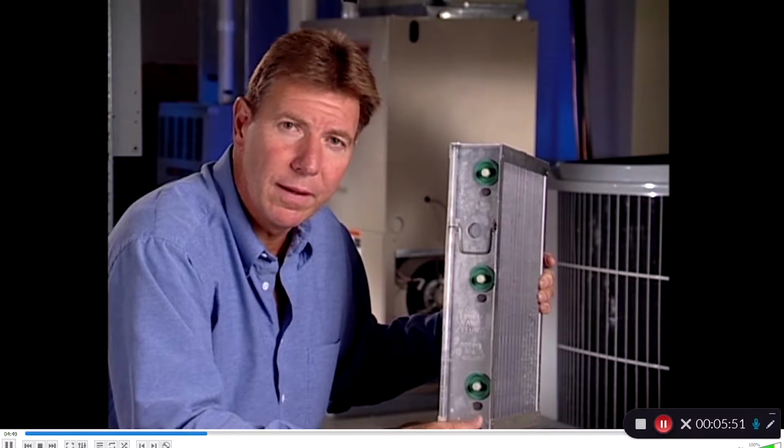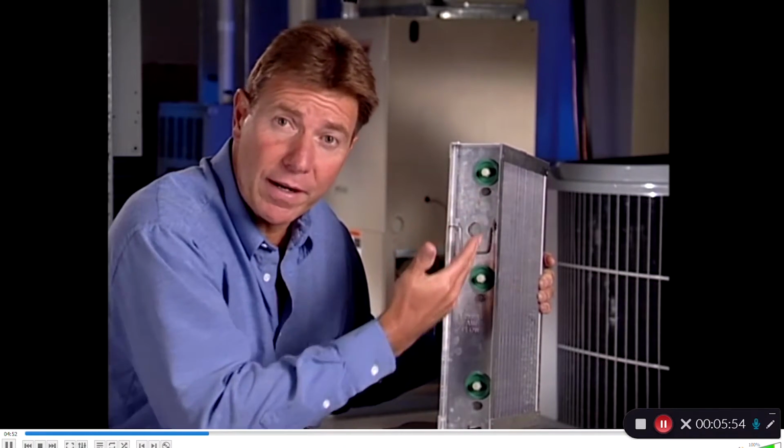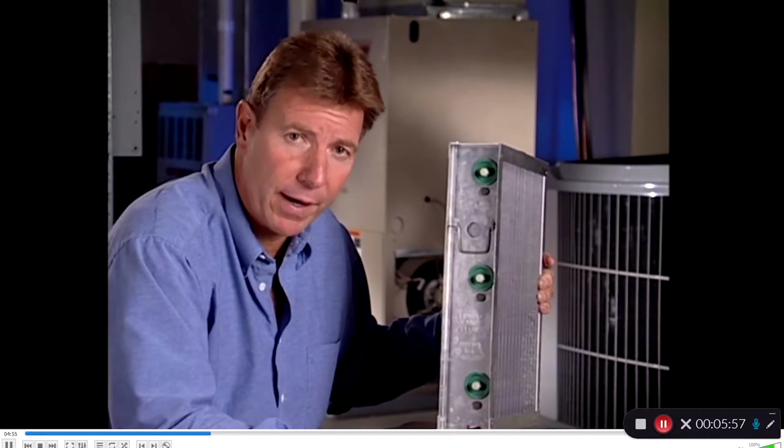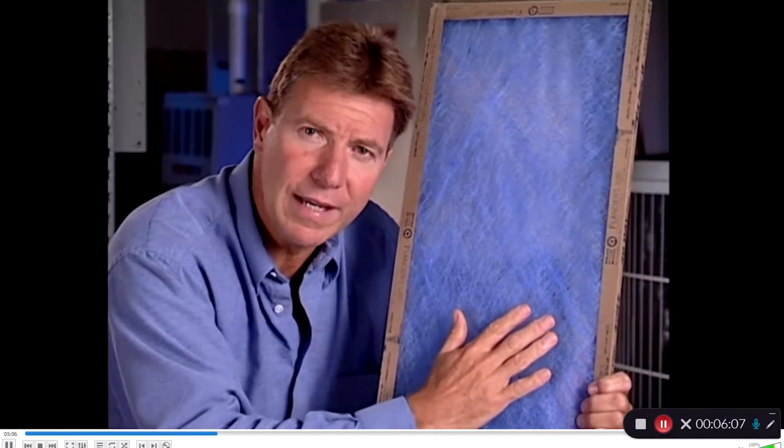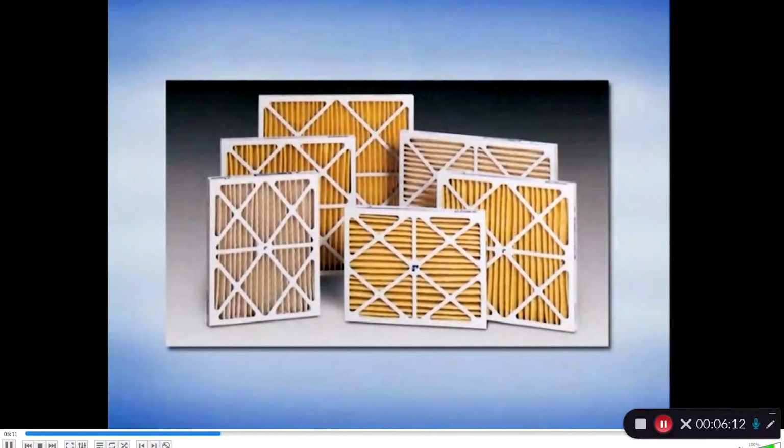Air cleaning can be accomplished in a number of different ways. Mechanical filters and electronic air cleaners are among the most popular air cleaning methods in use. Fiberglass filters are typically mounted in cardboard frames and are a disposable filter. They are coated with a dust-holding adhesive that helps prevent particulates from migrating downstream. Pleated filters, also called extended surface filters, are made of a cotton-like material that can accumulate heavier, more restrictive particles at the bottom of the pleats, leaving the sides open longer for effective filtration.